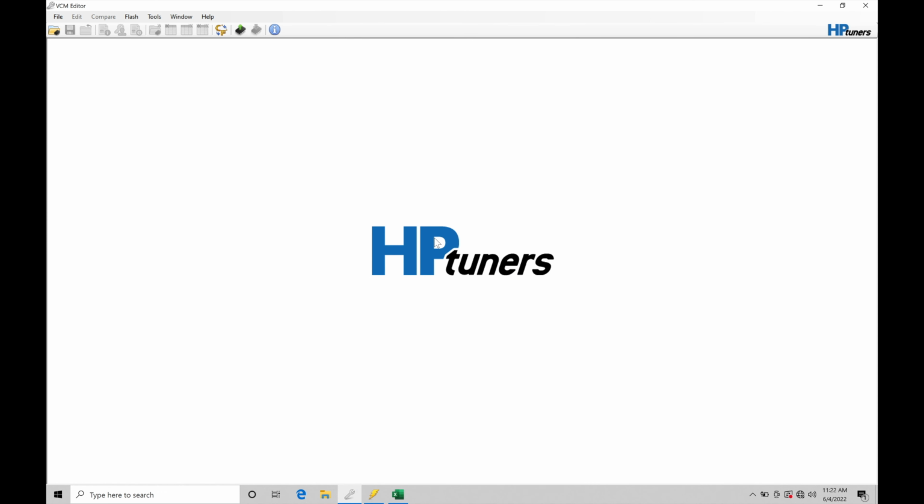Okay, so let's get started. We're going to be taking a look at working with our closed loop fuel correction in our Gen 2 Ford Coyote applications. Our closed loop fuel correction makes sure that we're always delivering the proper target EQ ratio or target air fuel at any given operation point as our engine is running.